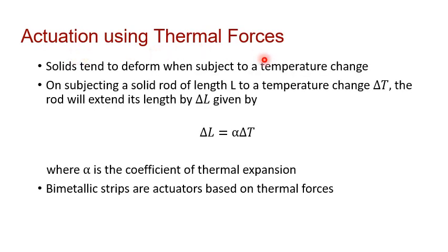Actuation using thermal forces. Now, most solid materials, when subjected to a temperature change, have a tendency to deform. So, for example, if you consider a solid rod having a length of L, and if it is exposed to a temperature change of delta T, then the length of the rod will extend by delta L, where delta L is given by delta L equals alpha times delta T, where alpha is the coefficient of thermal expansion.